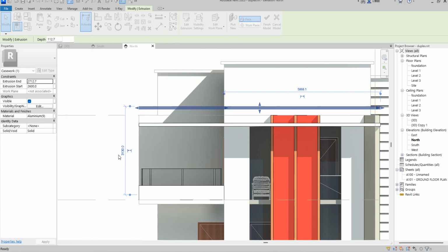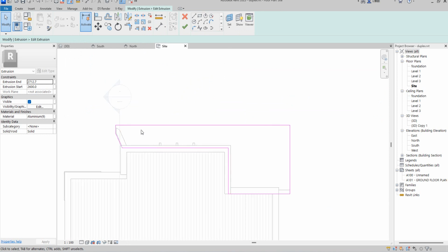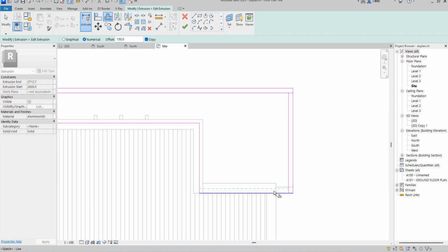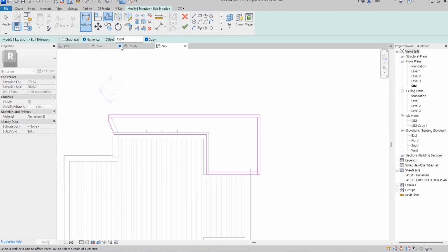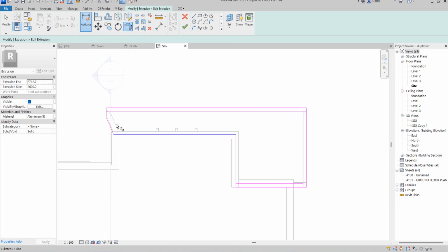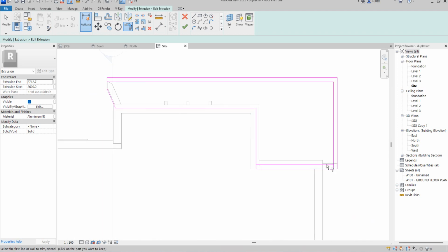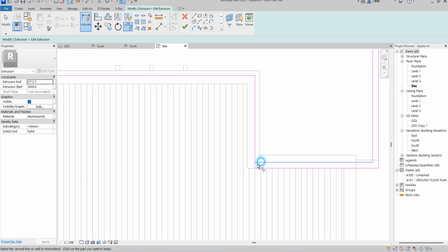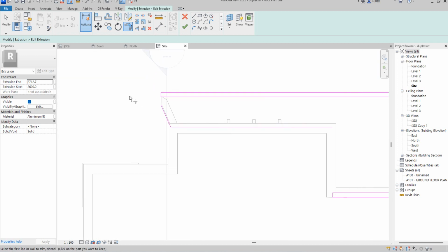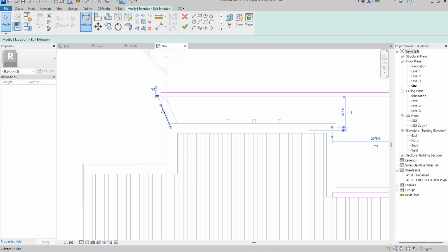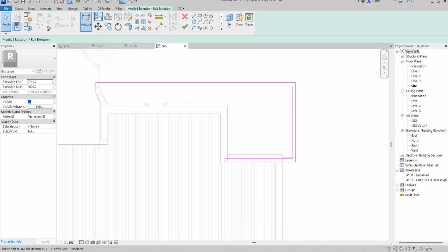Let me use site so that we see everything completely. Now I will offset the normal size 150. Then with copy, I'm going to do copy only of the side I want to work on. So now I'll do by cutting it off here. Cut it off here. The same thing here. So I'm going to remove the extra parts while I lay this one to the edge.